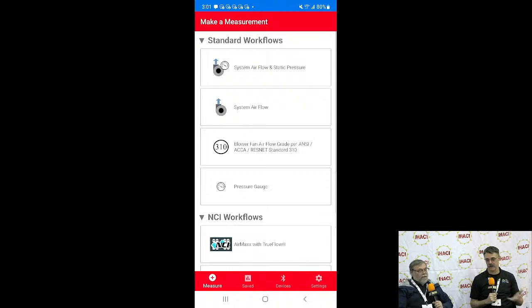And this one is now the digital TrueFlow Grid. This one's much easier to use. It is actually even more accurate than the original one. Right, so definitely some benefits. It works with Bluetooth, so you get all the stuff on your phone, which makes it really easy to build reports. Right. Take all the static pressure, static profile a system.